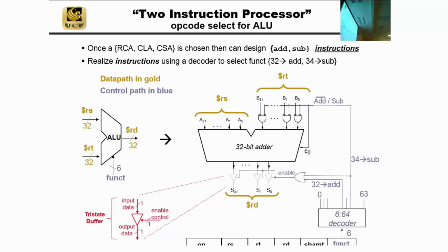Why? Because it's a contradiction unless you can guarantee that they're always the same. If the one input's a 0 and the other one's a 0, you can connect them together. There's no conflict. But if they can sometimes differ, one transistor is saying it has to be 0 volts, and another transistor is saying it has to be 1 volt or 1.2 volts. It's a wire. It does whatever the transistor says. The electrons follow. So there's a contradiction. It can't simultaneously be 1.2 volts and 0 volts at the same time.